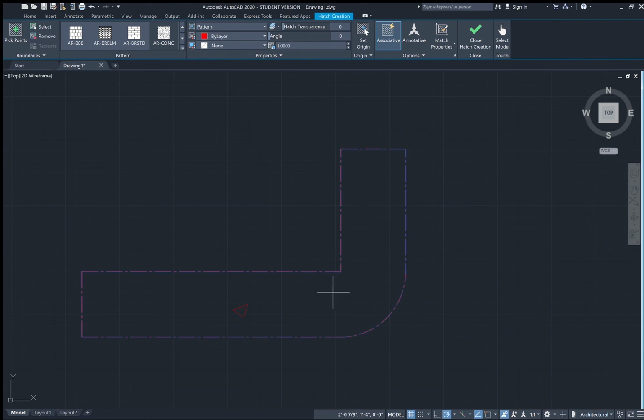And as you can see, we only get one triangle here, and you're probably wondering, why is that? That's because our scale here is set to 1, and that's very zoomed in. If we were to set the scale to 50, we zoom in even further. And so we don't want that. We want it to show on our graph. So let's say we chose 0.05 scale. Now, as you can see, the concrete hatching is a lot more defined.